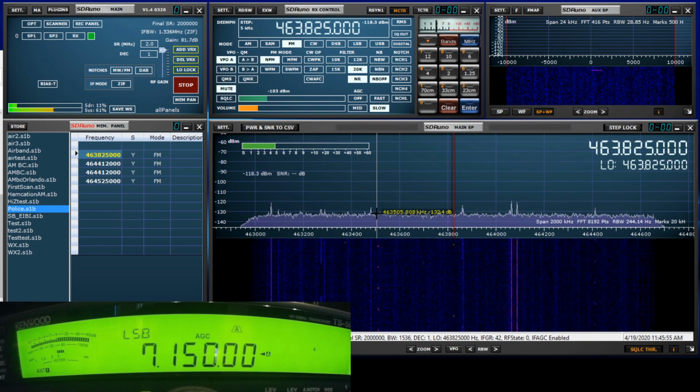And the answer is yes, you most certainly can. So you can select inputs. You can select one antenna input which is connected to your rig when you want to use it as a Panadapter, and you can use the other input when you want to use it for covering frequencies outside the range of your rig.